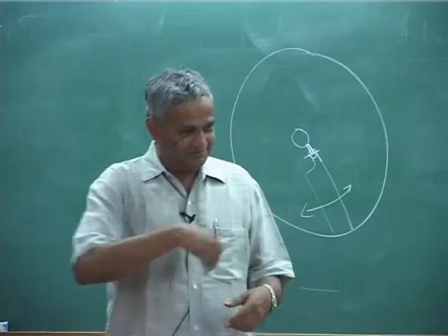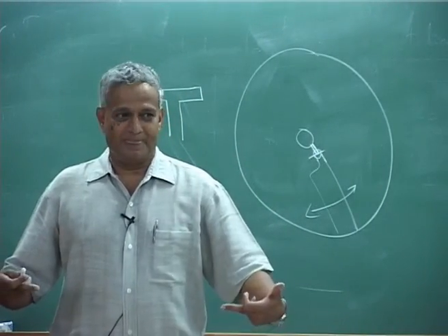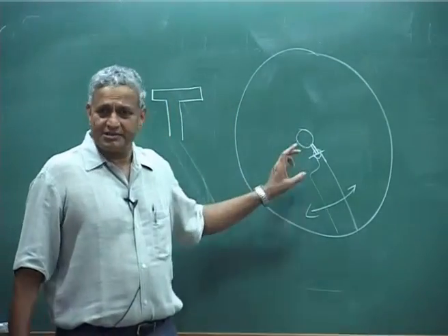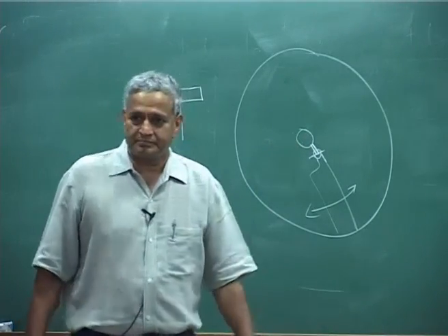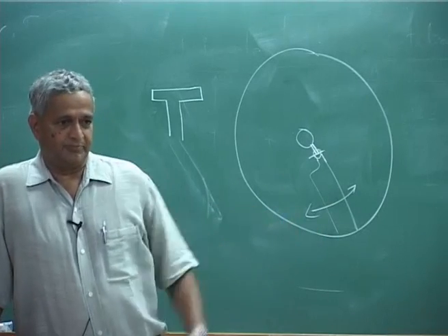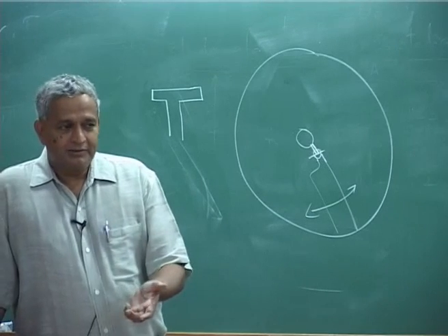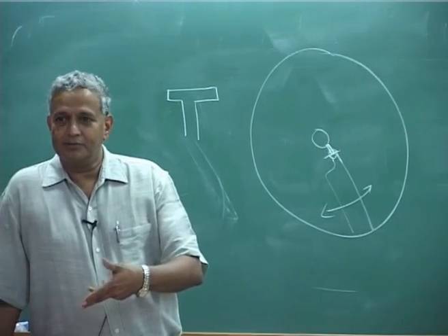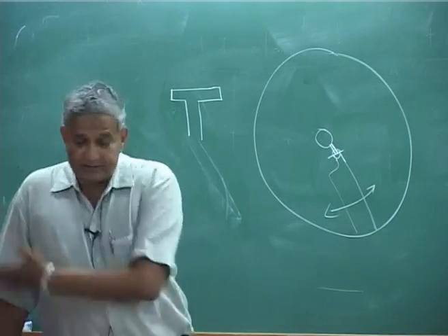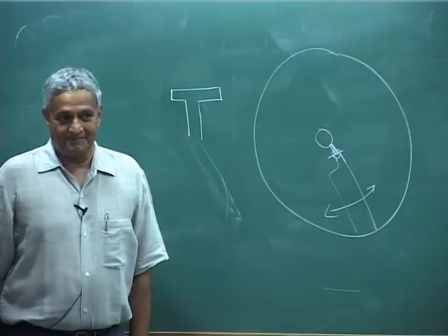Always you will find that transfer of power is there, by the offset, but this offset is decided. Most of the rotors will have it. So we effectively want the force to get transferred to the hinge. The hinge is a good design because you do not transfer the moment, but if you do not transfer anything at all, then how will you rotate in the first place?